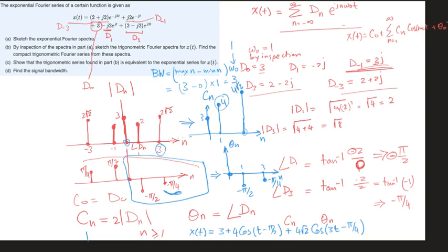in that case, again, for any real signal, you will have the negative and the positive. We are not dealing here with time domain complex signals. So if it's -2, you will always have the positive 2 as well. So in that case omega naught is 2. If that's the lowest that you figure out there, which is 2, then omega naught is equal to 2, because you assume that the lowest one is the one with n equals 1. Okay?